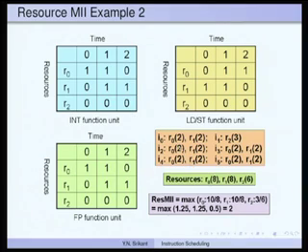So, now if you sum up all the R0 requirements, you get 8, all the R1 requirements, you get 8, and R2 requirements, you get 6. So, this is the number of resources. R0 is available in 8 units, R1 is available in 8 units and R2 is available in 6 units. Why? We have 2 integer units, and R0 is required in 3 phases. So, we would say we have 4 into 2, 8 of these, and R0 is required here also 1 and 2. As I said, this should be zeros, only these should be 1s. Now, R1 is required, and we would have 8 resources again, because 2 of this and 2 of this, 4 into 2. So, again 8 resources, and R2 would be available in 6 resources. If this is 1 1 1 each, we would have 3 of them, and then into 2 would be 6.